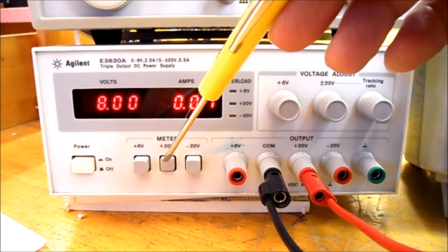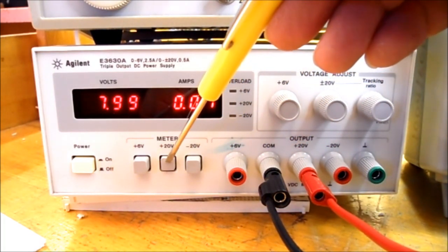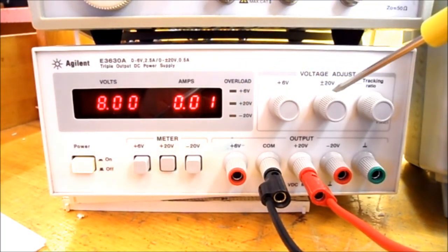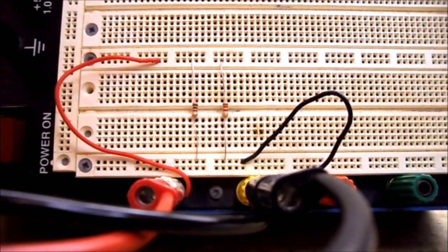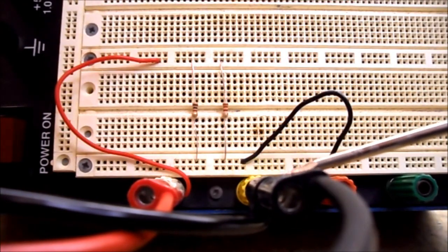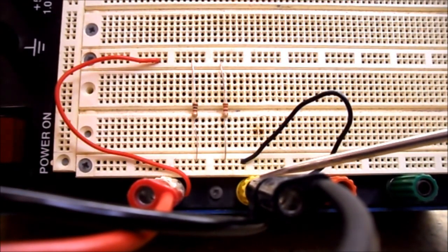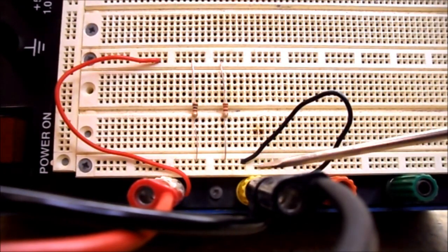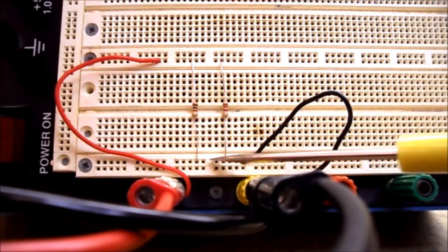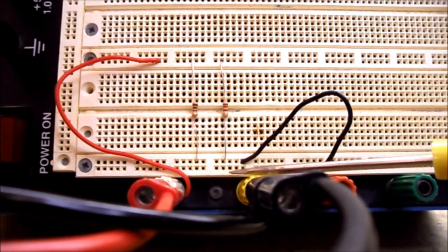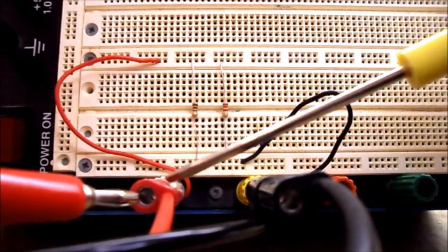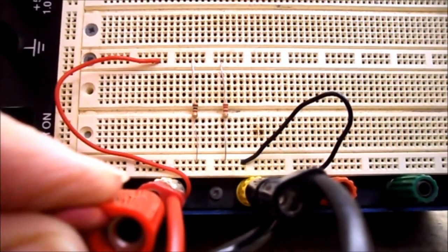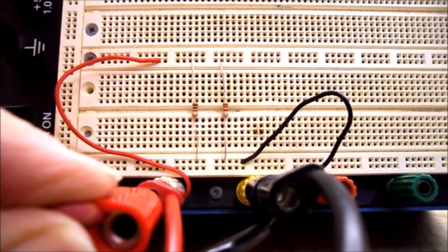Remember, we're going to be using the plus 20 volt terminal, so press in the plus 20 for the meter and use the plus 20 volt adjustment knob to get to 8 volts. So to measure our DC voltages, we're going to put the black lead from the voltmeter into the black lead that comes from common of the power supply and goes to the black lead in the bottom of our resistors. Now the red lead we're going to place at point A, and point A is at the back here where it comes in from the power supply.